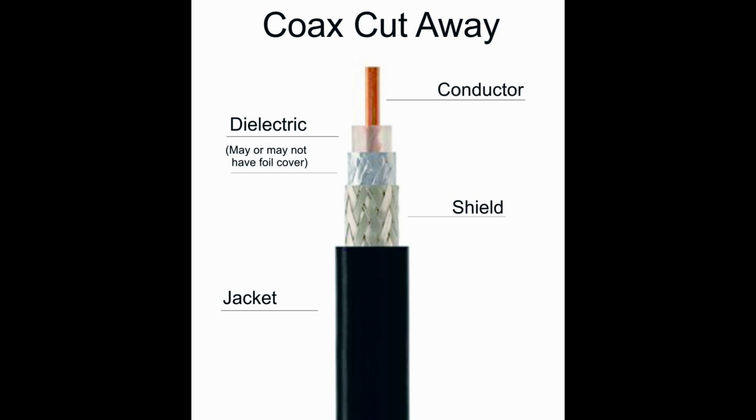At the core, coaxial cables consist of a single copper or copper-coated steel wire. It's what carries the RF signals. A dielectric insulator, often made of plastic, surrounds the wire. It keeps a constant distance between the center conductor and the next layer. The metal shield made of woven copper, aluminum, or other metals, wraps around the insulator. It cancels outside electromagnetic interference. Some coaxial cables are constructed with multiple shields for extra protection. The final layer is a jacket that protects the whole configuration. Its rating lets you know where the cable can be installed.